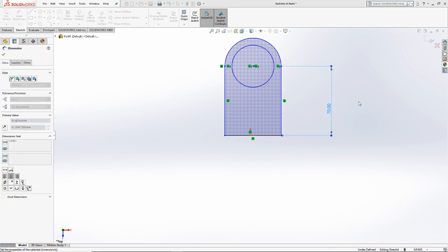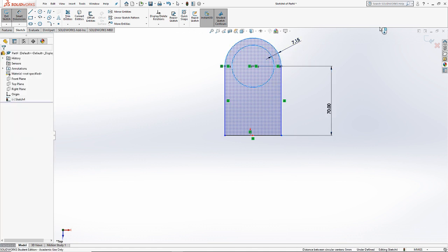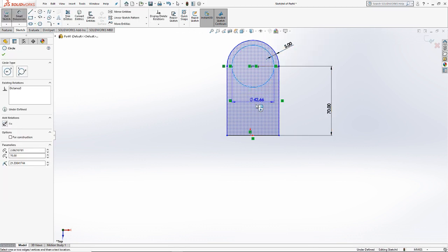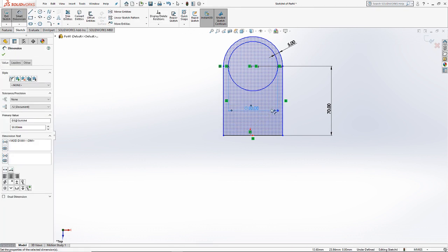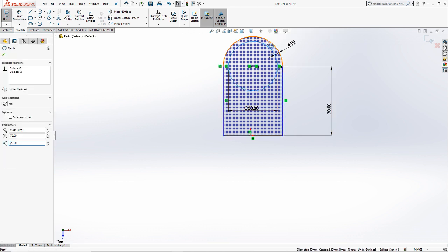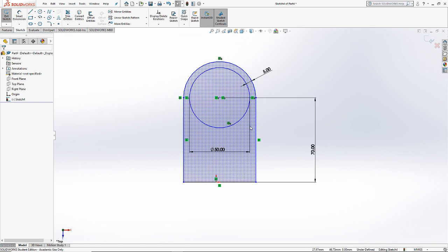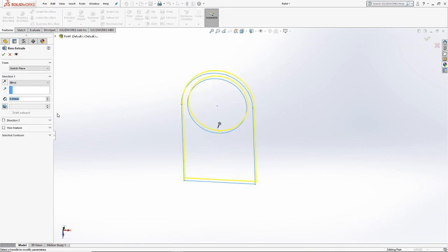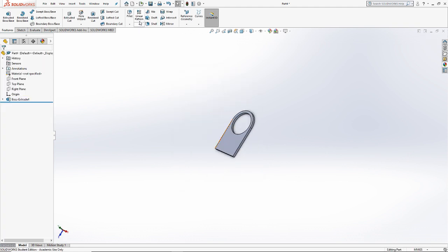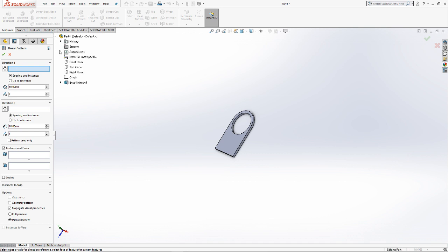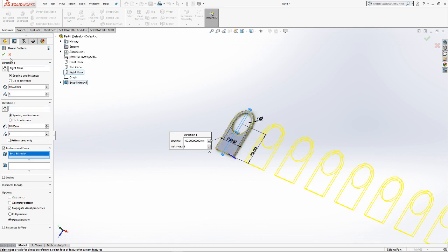That's really my favorite part. So I'll apply some arbitrary dimensions. Maybe this is some sort of 5mm thickness. And that, yeah, that looks good. I like that. Now, when I go to try to create a pattern from this sketch, I don't have anything to revolve around. That's all okay if I'm creating a linear pattern. I can reference the existing planes for that. I could say create a linear pattern in the right direction. Pattern these 100mm apart and make a bajillion of them. That would work just fine.